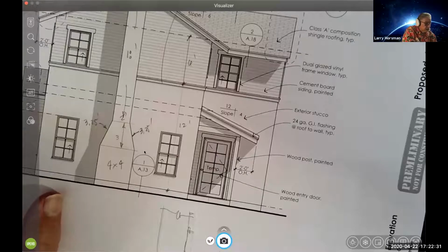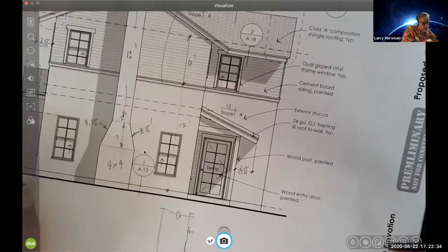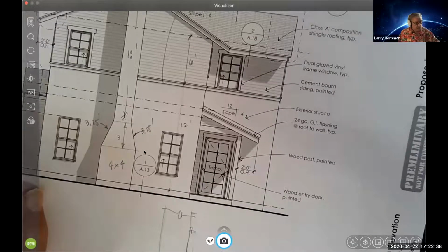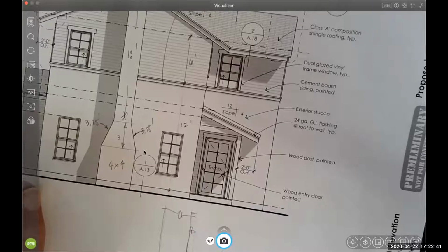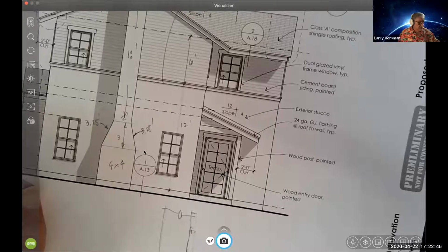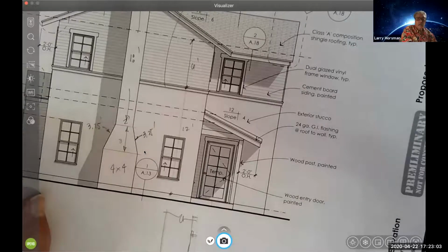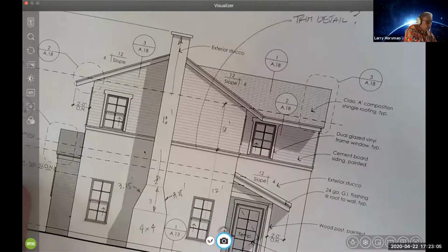So I generate something. Now for the siding takeoff, and I've done the siding takeoff, I just ignored the openings. They're not huge on this, and every time you have to cut stuff up, it increases the amount of waste anyway. So normally they just ignore the cutouts for that. And the area that often gets overlooked or missed if you're doing the takeoff is the gable end piece.